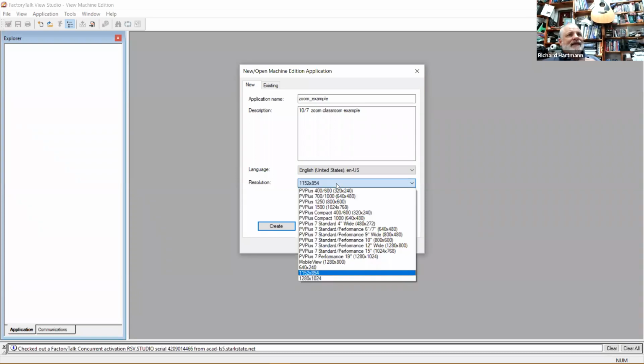So what this is going to do is set the display size of our HMI. But again, if you have a physical HMI like the ones we have in the cabinets in C202, you would have to select the appropriate one, because it also ties in the touch screen information so that you can press the button.